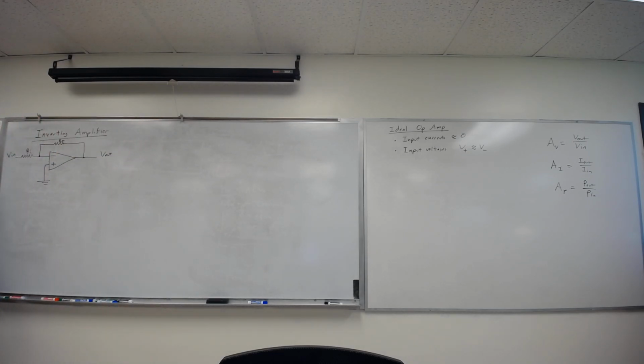Okay, real quick, I'm going to go into the negative. That means my output's going to be inverted, right? If I have a positive number in, I'll get a negative out. If I have a negative in, I'll get a positive out. And because this has so much amplification, it's going to frequently be more than I need, so I would go all the way up to the power supply or all the way down to the power supply.